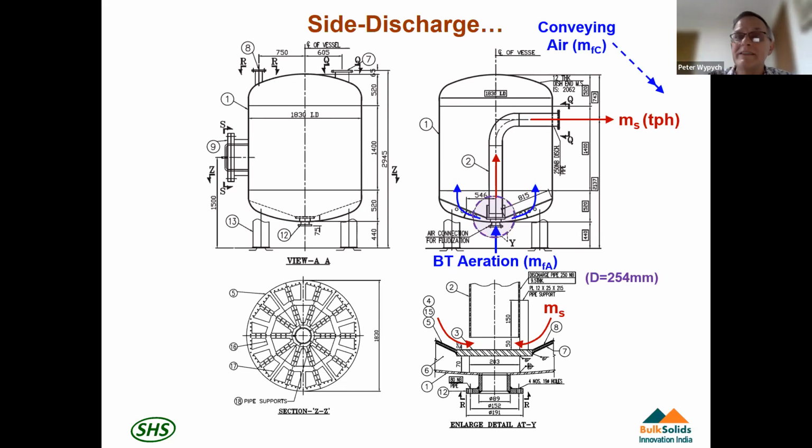So that small gap that you see there seems to be a standard gap used by this particular designer or manufacturer for all their blow tank sizes. And that small gap can be enough to restrict the capacity of the entire plant.